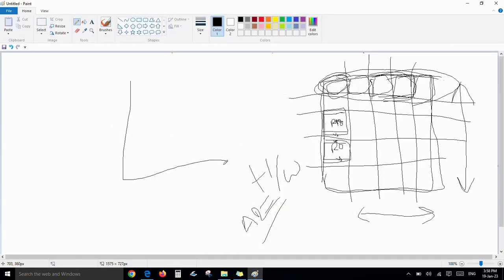If my macro is placed like this, obviously it fits here. If it is more than this, obviously it is not going to fit. The macro size should be multiples of unit tiles, or manufacturing grid multiples.